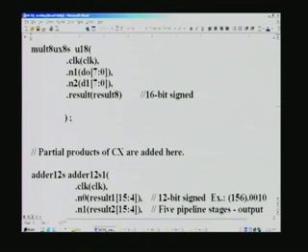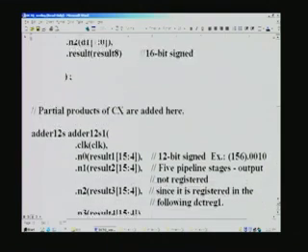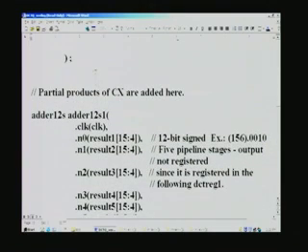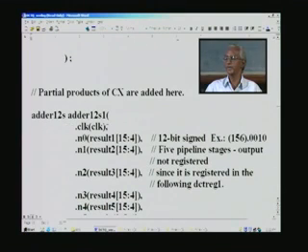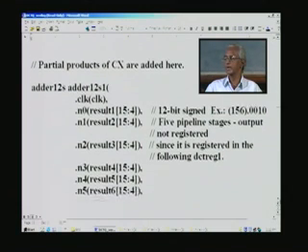And so at this step we have multiplied and got 8 results, result 1 through result 8, and the next step is to add these 8 results that we have got, by using adders which we have already designed before, and these N0 through N7 are none other than this result 1 through result 8 which we have got before. Note that we are dropping some bits here because that much precision is not really required.